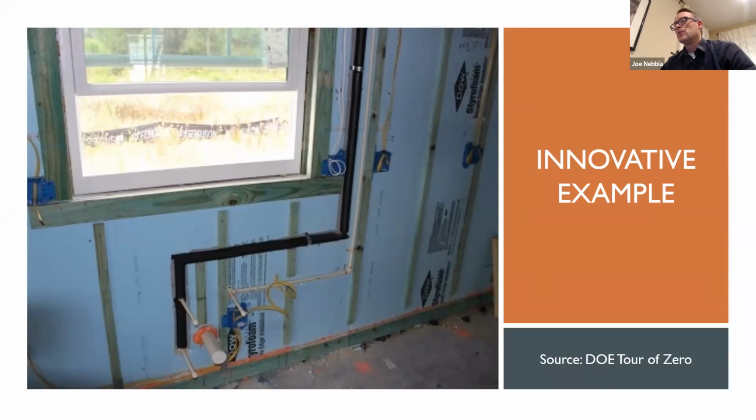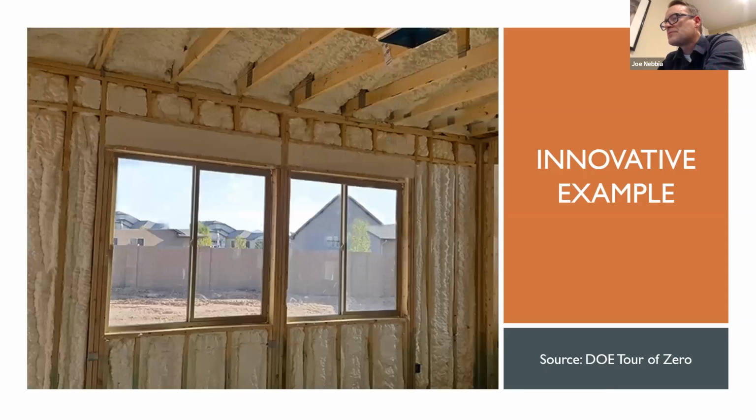This is rigid foam. In this case, it's to the interior. I'm not sure if this building had it also to the exterior or not. So the wood you see here, I believe, is furring strips for attaching the drywall and that sort of thing. So I believe this is a concrete block wall, but I'm not positive about that. And then you need an R6 if it's in climate zone 2 to the interior, or R4 on the outside.